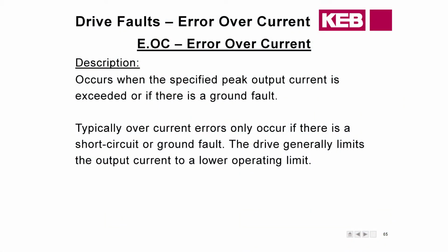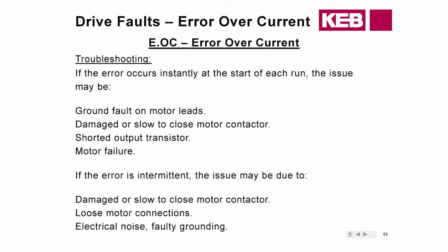All right, E.OC, error overcurrent. This means that there is a short or a ground fault somewhere, either on the drive or motor side of things. If you're wondering, is it the drive or is it the motor?